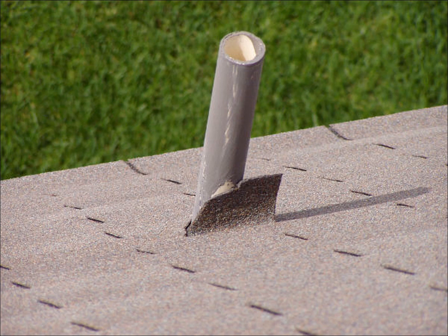There's a cricket on one of our roofs. Now, some of you look at that and think, wow, that's just a shingle that popped up and turned up. Well, see, that's where you're wrong. You're just not experienced enough to notice that it's a cricket, used to divert water around that pipe so the pipe doesn't leak. I mean, come on, what a sharp roofer.